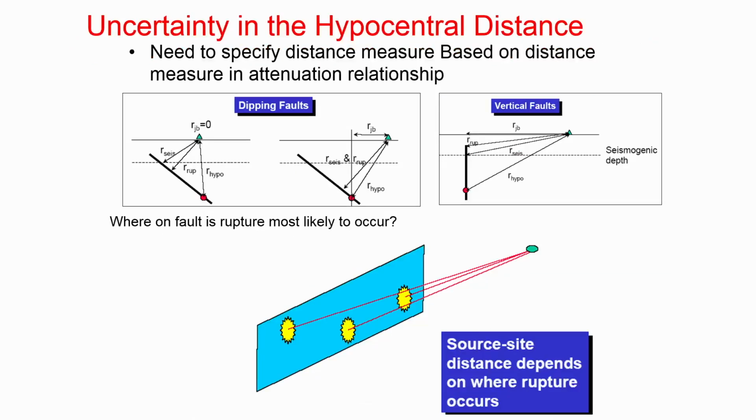That is, you repeat the same steps and finally arrive at summation values by varying the parameters. For example, as I told you, you take the minimum distance and then vary up to the maximum distance, each and every segment, saying my earthquake may occur here, then here, and then here, and what is the probability density function for each one and what is the possibility of occurring, which is modeled in the probability density function.